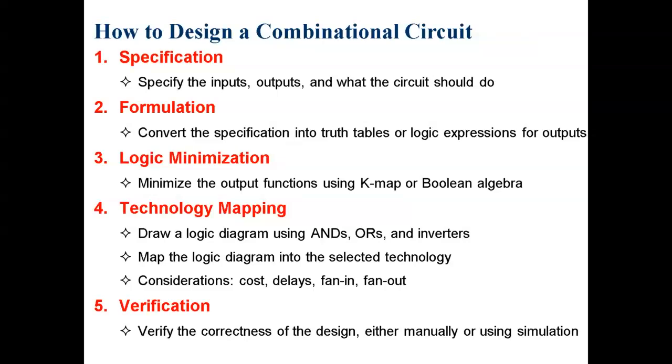So let's assume we want to have a half adder. What are the inputs? The inputs are x and y. What is my output? It is Si and Ci+1. This is my half adder, not full adder. If we want the specification for the full adder, what are the inputs? Ai, Bi, and Ci. And what are the outputs? Si and Ci+1. So this is the specification.